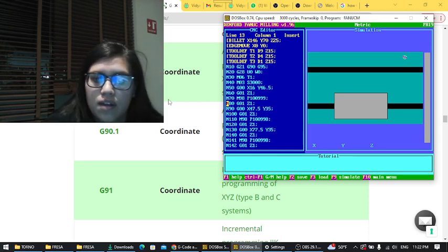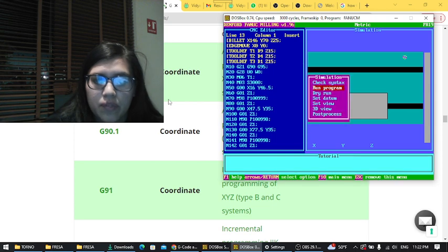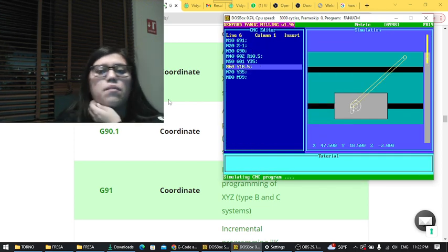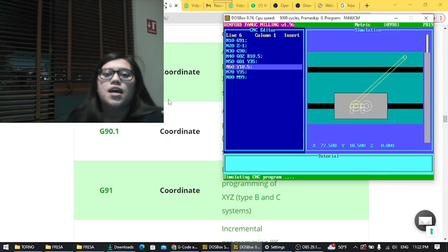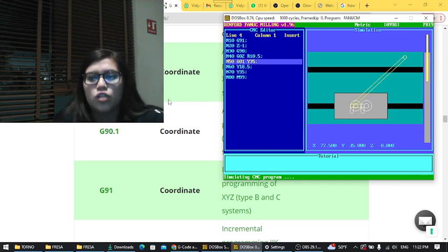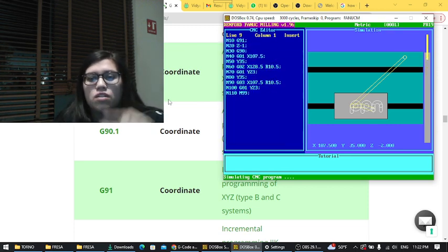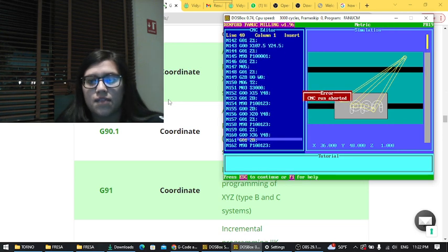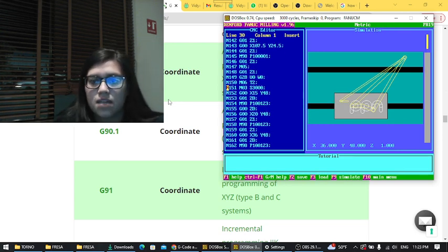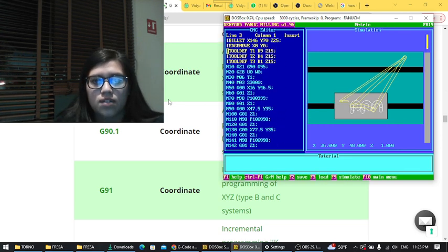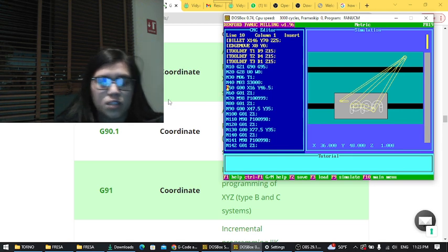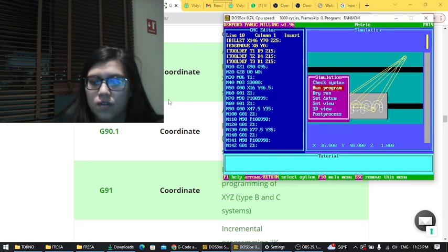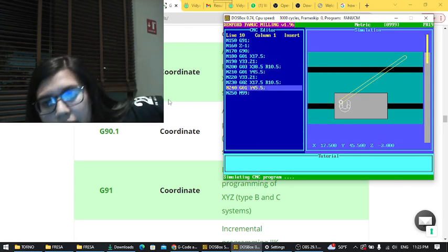So you have to run the program again, and you can start it at some point after N60, and it's going to go really quick. So I decided to just start on the piece so it can go real quickly and we can see how the U is made. Actually, I think I have to cancel that because since it's not actually cutting the U, I have to start it again right around here. It has to be after the spindle, and there you go. We're going to run the program. The U is established real quickly.